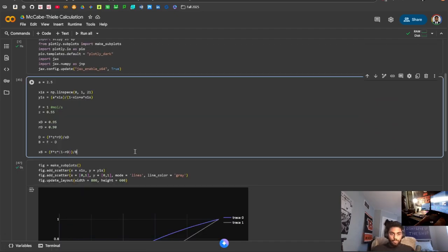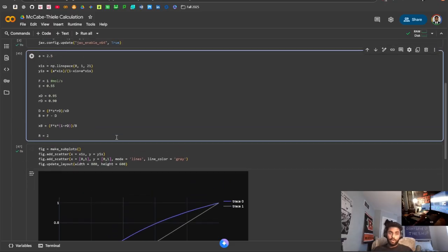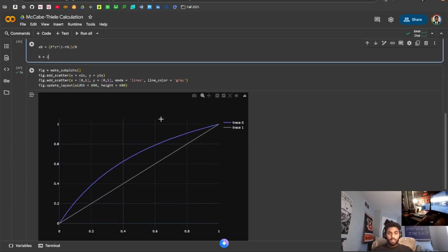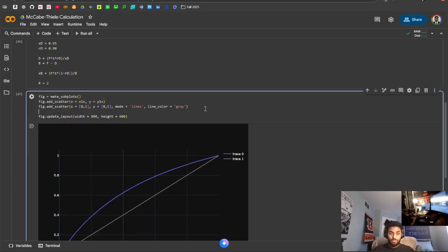So let's start out with our rectifying line. We remember that from the operating line equation for a rectifying line, we have something that we define as a reflux ratio. And so right now we can set that reflux ratio to kind of be whatever we want. So I'm just going to choose 2 right now. And that's pretty much all we need to actually graph out this rectifying line. So let's go ahead and do that really quick. So I just used this autofill to kind of get me started here.